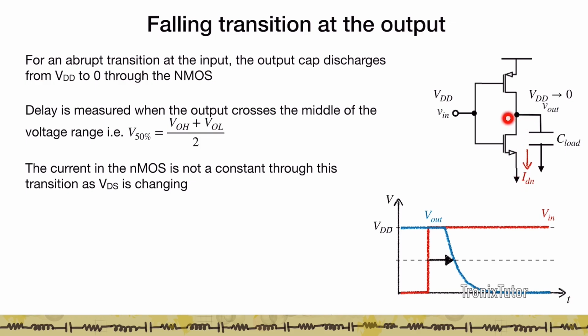So initially, when your gate is VDD and when your output is VDD, the NMOS is in saturation. But as the output voltage falls, the NMOS transitions from saturation into the triode region, and then the current has a Vout component to it. Right? So keep in mind that during discharge, it's not always that the NMOS works like a current source. It in fact has a combination of a current-source-like discharge and a resistive discharge.